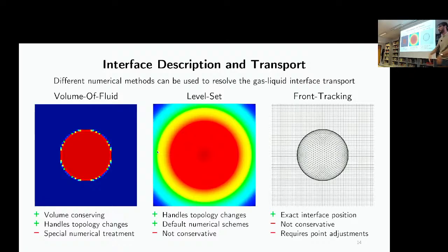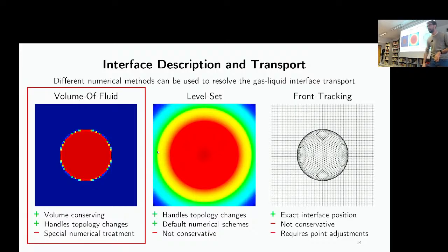Okay, so let's see how we resolve this set of equations, starting from the core of each multi-phase model, which is the representation of the gas-liquid interface. There are different methods that were proposed in the literature to describe a gas-liquid system: volume of fluid, level set, front tracking. There is still development in this area. But we decided in this work to use the volume of fluid model because among these it is the one that is mass conservative by design.